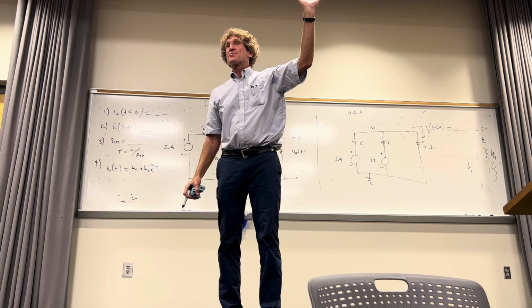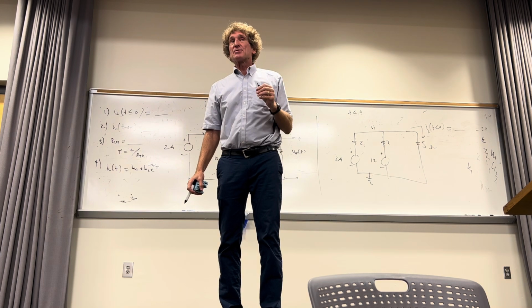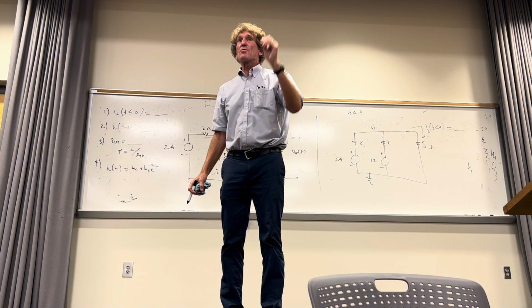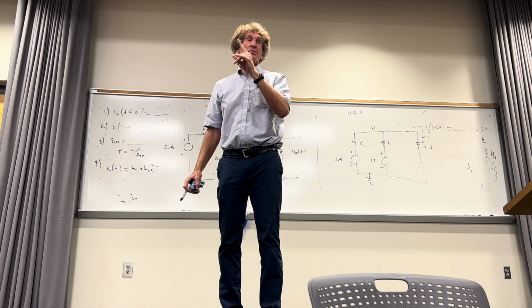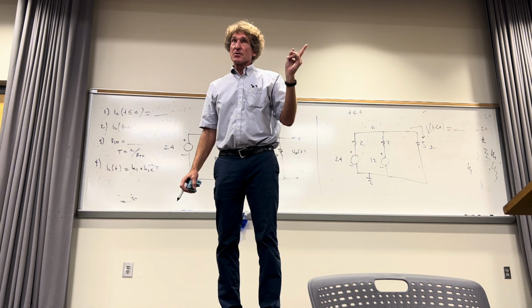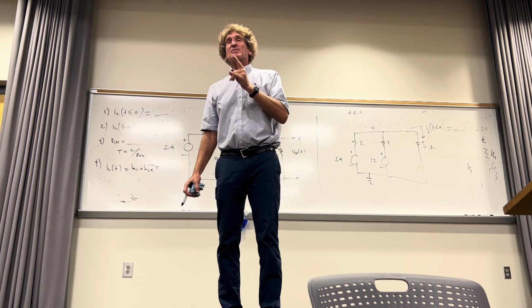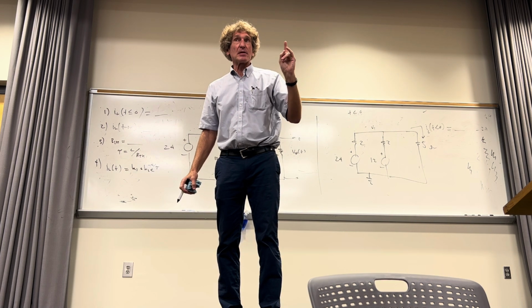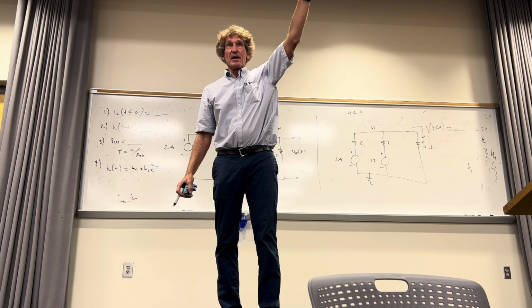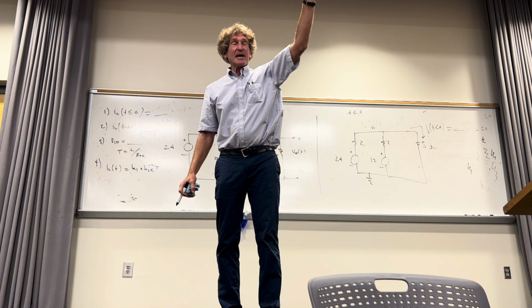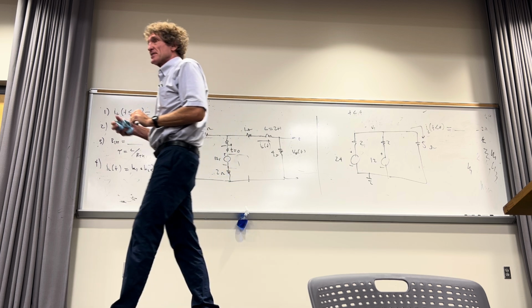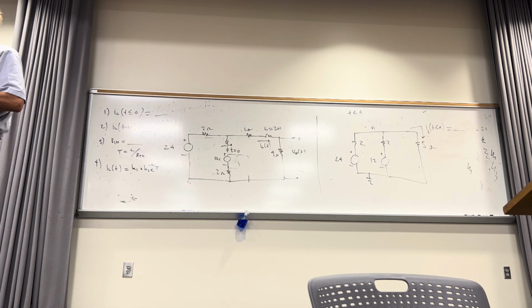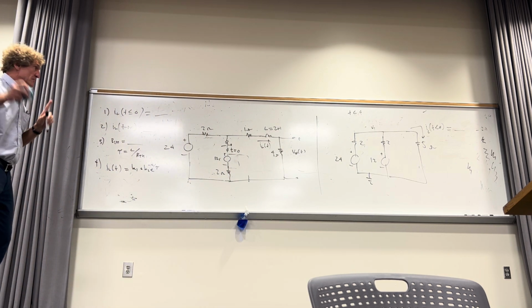I'm going to show you a trick. Remember I showed you the Thevenin to Norton conversion: a voltage source in series with a resistor turns into a current source in parallel with a resistor. How many remember that? Good. That's the guy you want to go to. These are tricks you're going to find very useful solving this type of problem and problems to come.